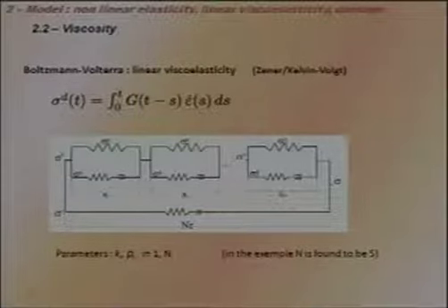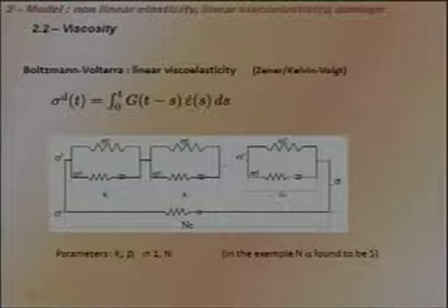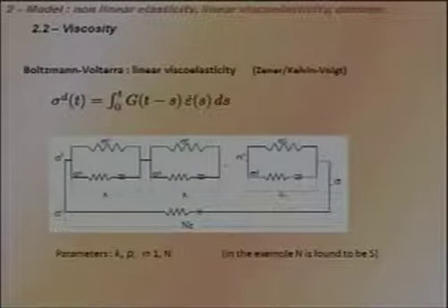That's the reason we began to work on that. Finally, this turned out not to be convenient, and we turned to linear viscoelasticity first. So with that kind of model, the Kelvin-Voigt or the Zener models, that's for each layer, and the global viscosity in parallel to everything.